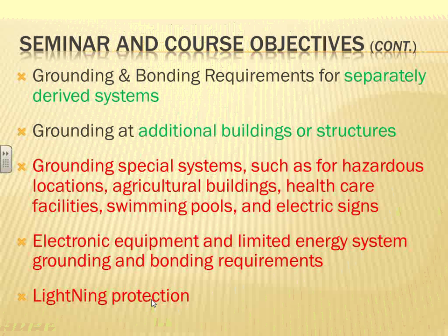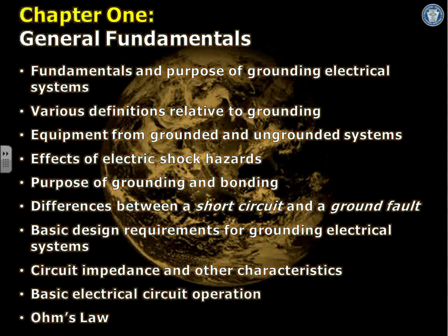Again, and also lightning protection, guys. That's why I said you walk into a building and you find them bonding and grounding with 500 kcmil, because they take into consideration a whole lot more than just the electrical system. The lightning system is a big protection tying it together, and the low voltage system as well.